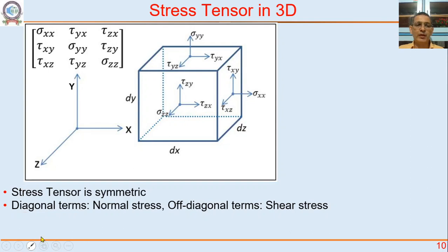Let's say we are talking about orifice meter. There is a pipe here, there is an orifice meter here, orifice here. The flow is going in this direction, right? We said that cross-sectional area is reducing. Cross-sectional area is reducing, velocity is increasing from here to here.